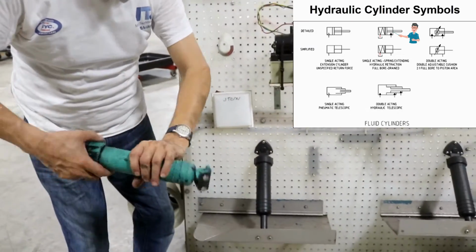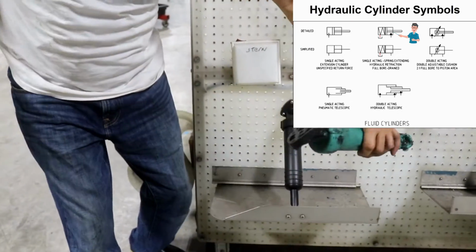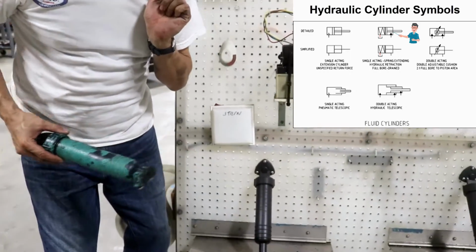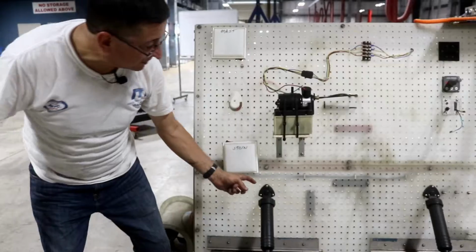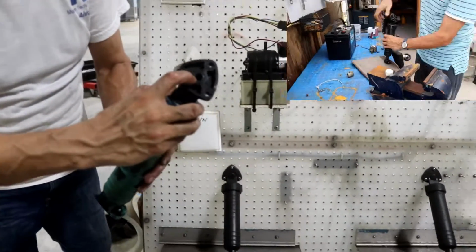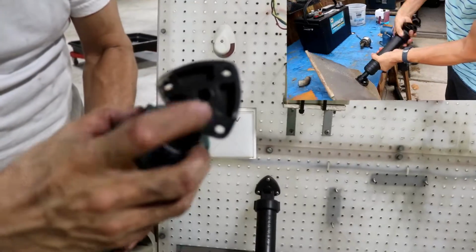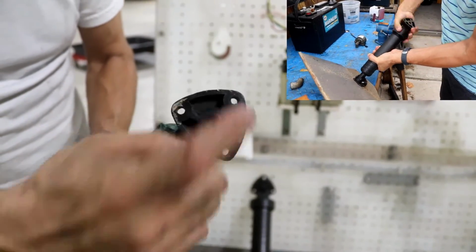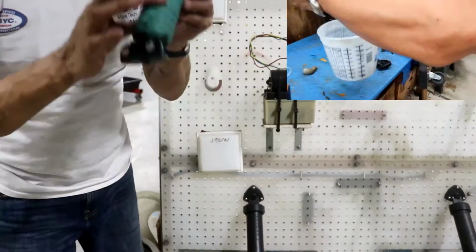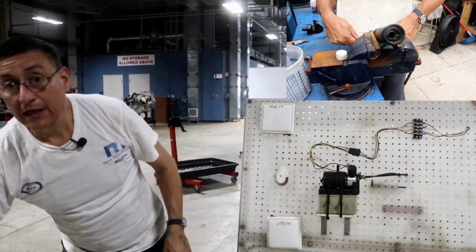If I open this element here, a big spring is extended, like the picture that you have on the screen right now. This is a single port because the fluid enters over there and returns over there. This is the only port that we have. The fluid enters and returns. This is a single port, spring return actuator.